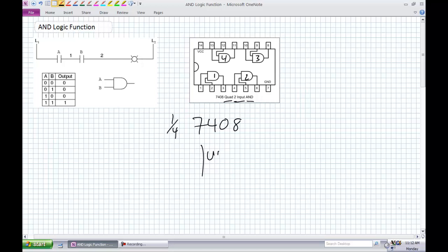Let's pretend that you only have one chip. It's a U1. The reason you use that fractional notation is for when you're designing a circuit. Say you're using 1/4 of a 7408, and in another portion of the circuit another 1/4, and in another portion 1/2 of a 7408. How many 7408s do you need? You need one. It's just a means of getting all your parts ready.